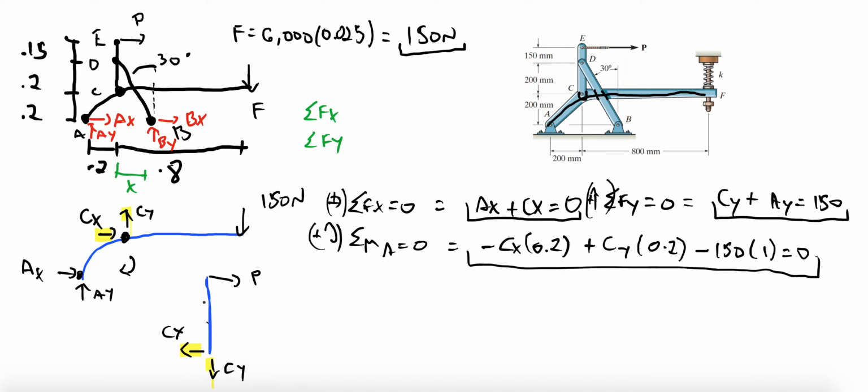Anyways, the only missing piece is the force at pin D. The interesting thing about this problem is that link BD is considered a two-force member. If you remember from trusses, the property of a two-force member is that the force goes right through the member. It acts as an axial load, which means that we don't have to draw it as, for instance, Dx and Dy.